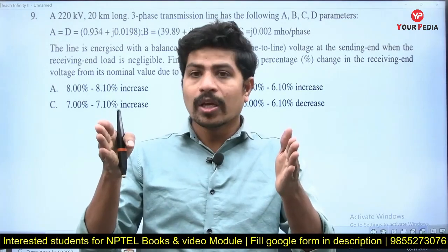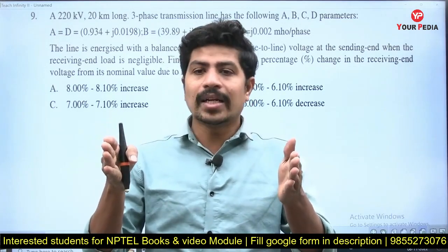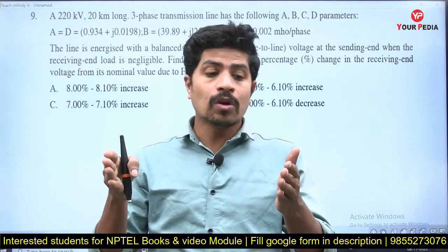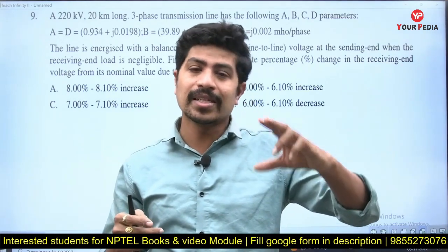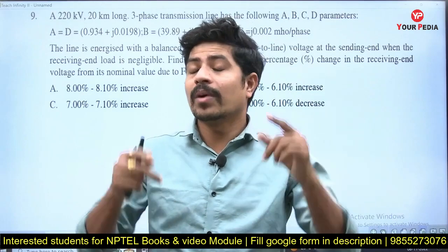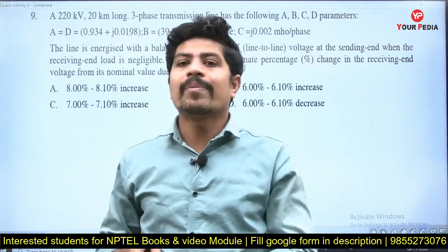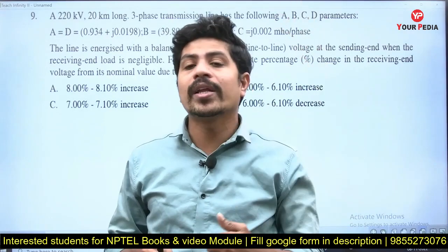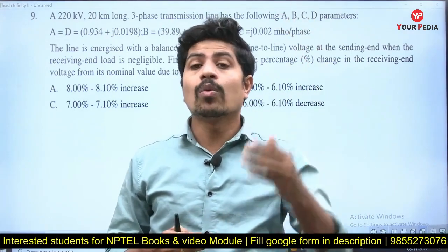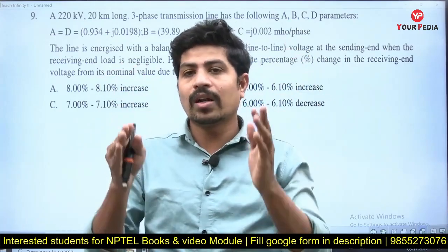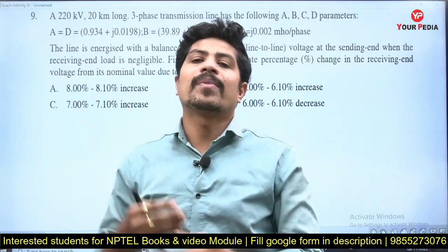And for capacitance, between two lines a capacitance will form. Yes, it is line to line capacitance, but the relationship of line to line capacitance to line to neutral capacitance is not the same as that of voltage for a star connection, where line to line voltage is root 3 times the phase voltage. That type of thing will not exist for RLC parameters.